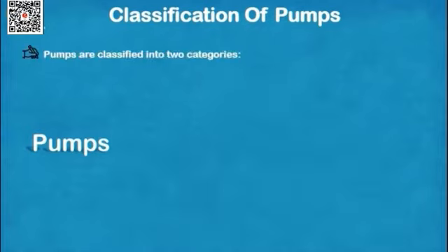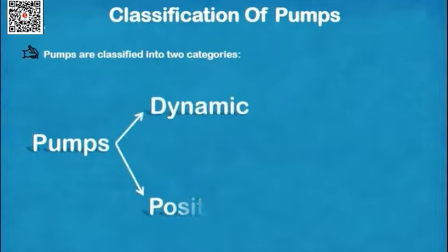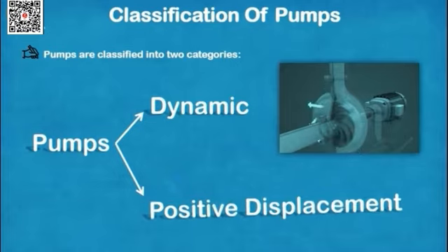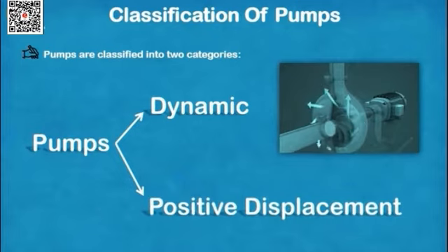Pumps are divided into two fundamental types based on the manner in which they transmit energy to the pumped media: dynamic or positive displacement. In dynamic displacement, the centrifugal force of the rotating element, called an impeller, imparts velocity energy to the fluid, moving the fluid from pump suction to the discharge. On the other hand, positive displacement uses the reciprocating action of one or several pistons, or a squeezing action of meshing gears, lobes, or other moving bodies, to displace the fluid from one area into another.